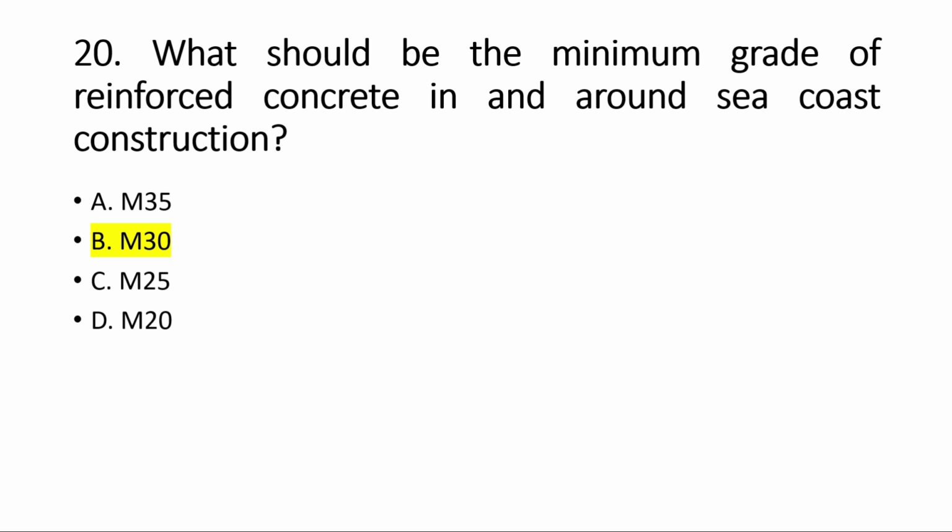For the minimum grade of reinforced concrete for mild exposure, it should be M20. And if we have a moderate exposure, then our minimum grade of reinforced concrete will be M25. So keep that in mind. And for severe exposure condition, we have a minimum grade of concrete as M30.